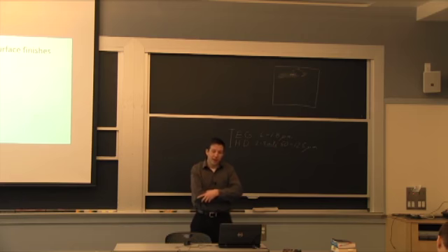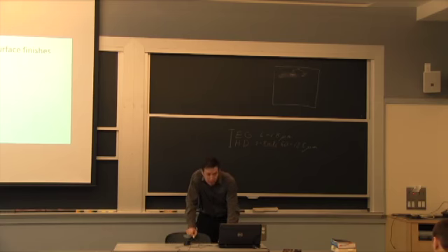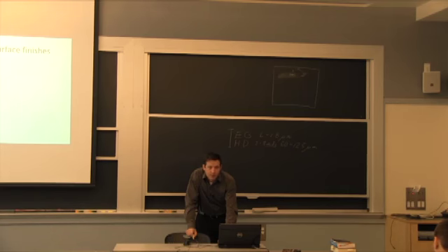Not that you can't paint it, but just galvanizing per se with piping, you're looking at about 50 years of life. And there is an initial cost, but you're not as sensitive to scratches and installation issues.